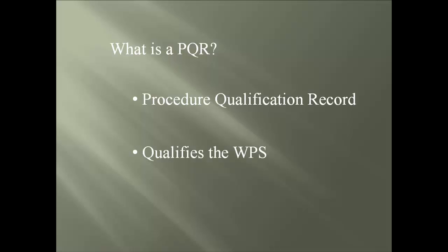Next, this living document qualifies the WPS, and once again we will cover the WPS in detail with the next segment. And lastly, as of 2010, the D1.1 has provided a new table that covers the essential variables that must be complied with, or the requalification of the WPS is required immediately.